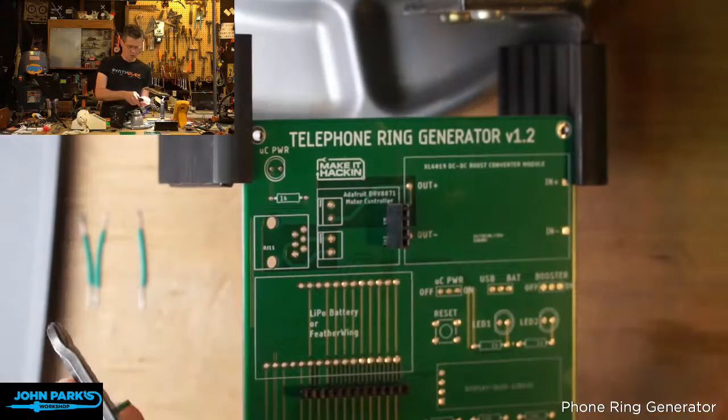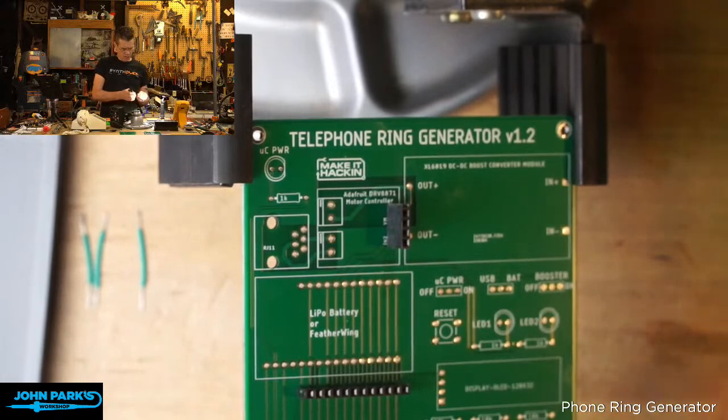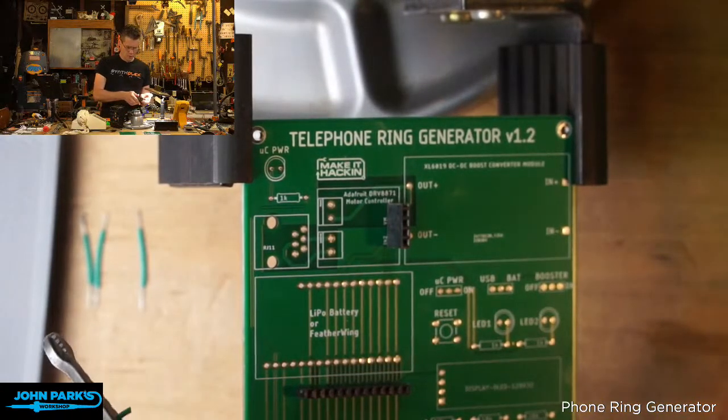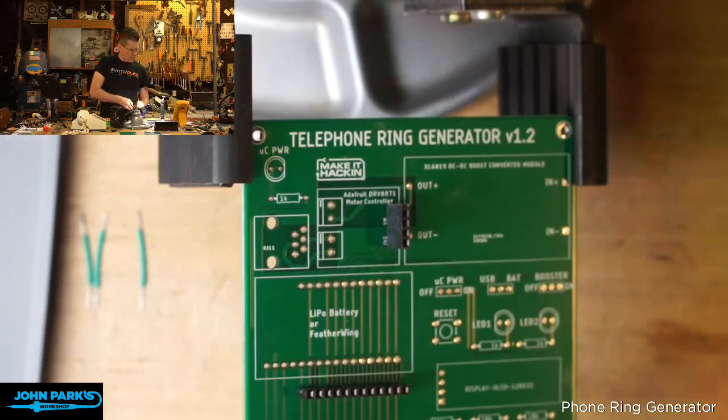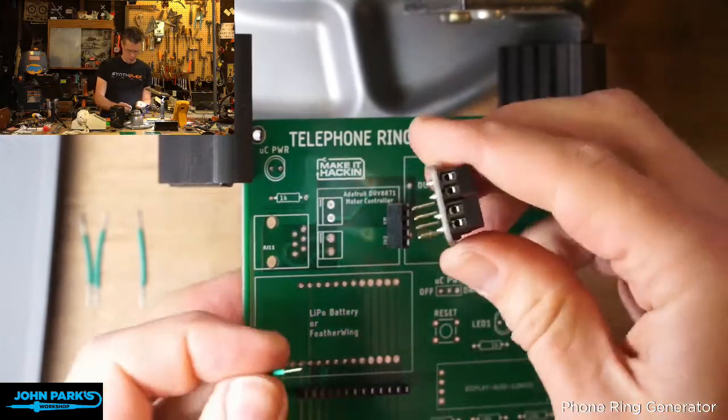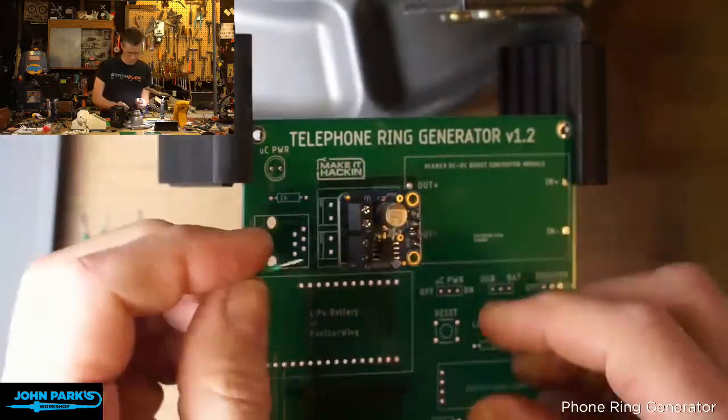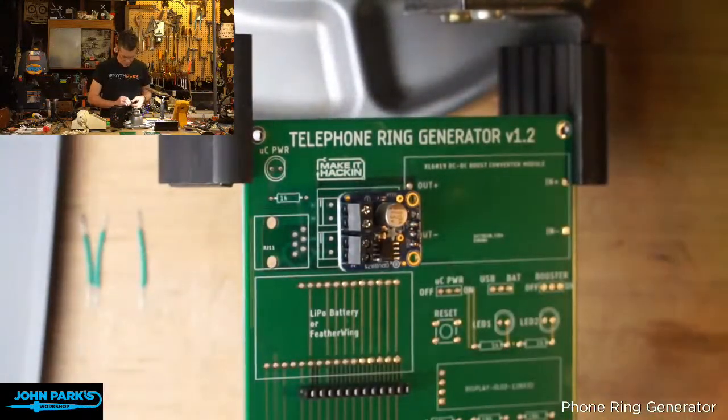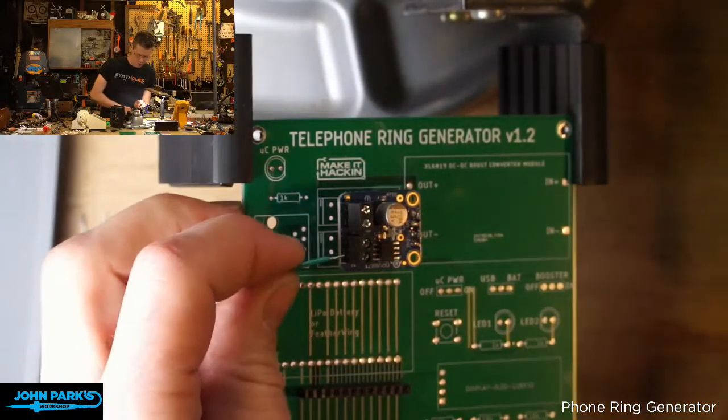By the way, if you're concerned about frayed ends of stranded wire in your terminal blocks, I do like those little wire ferrules that you can crimp. That gives it something to squish down against, which is what the screw terminal wants to do. Those are nice. I used those on one of those other phone projects.